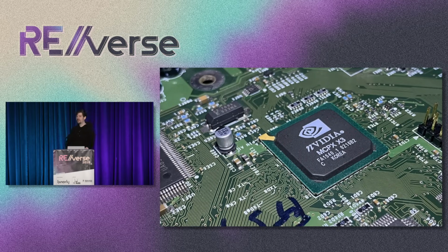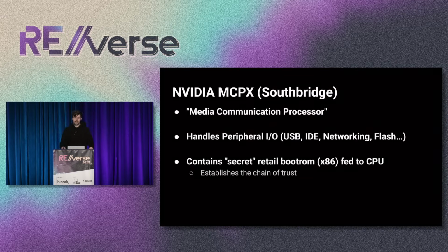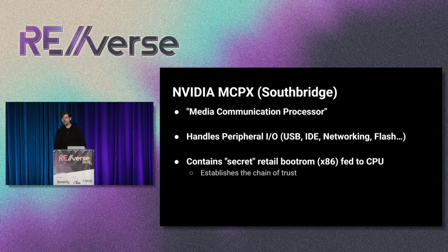If you've ever heard the story about how NVIDIA had to trash a bunch of chips and almost went bankrupt because Microsoft was like, oh, we don't want those anymore, they have an insecure ROM in them, it was this chip. The NVIDIA MCPX stands for Media Communication Processor, and South Bridges typically are responsible for handling peripheral I/O of your computer, things like your USB ports or networking or IDE or SATA or access to flash or the BIOS chip. You don't want your Ethernet wires going straight to your CPU, right? You would need a million pins off your CPU for all the various peripherals. And so everything usually would go through the South Bridge.